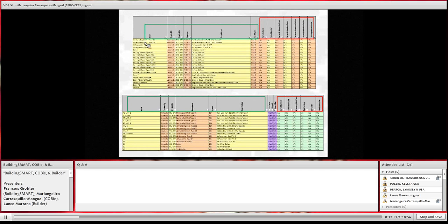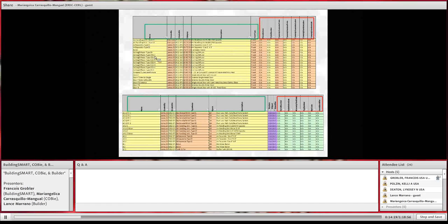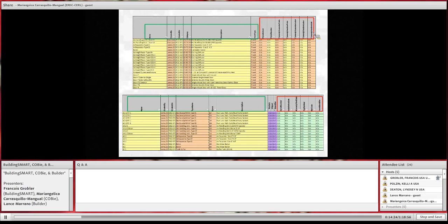So either you create it yourself or you export it, you have this design file. And this specific one is actually from a district of the USACE. It's from the New York district, and it's a project that is currently going on using COBie. So it's the New York battalion. So this is the design. In terms of the types, you have your types with your description, and all this information here marked in red is missing because it's design. You don't get that until later.